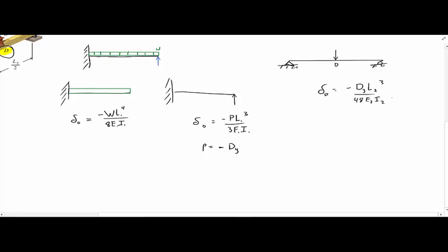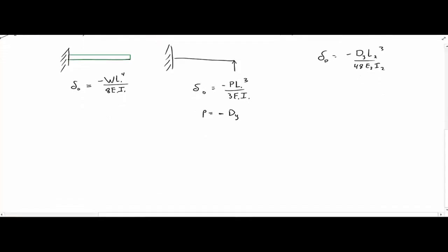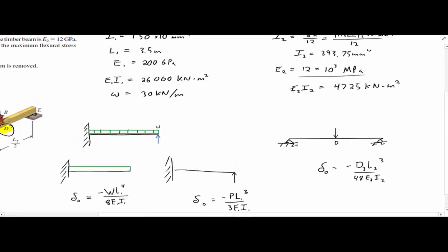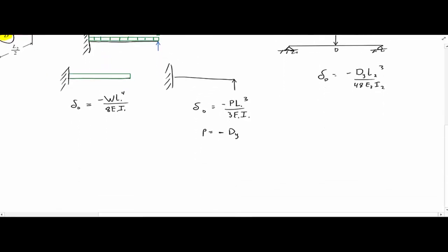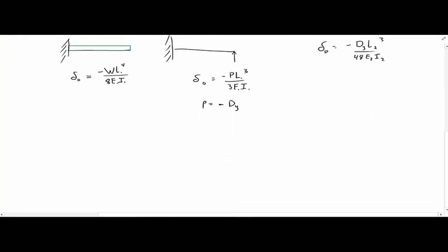So the deflections are going to be equal, or rather, we can equate them together to solve for the unknown, because everything in these equations is known. The distributed load is known, the lengths are known, the modulus of elasticity and moments of inertia are all known, and I even multiplied them together up here so they're already done. The only unknown is the reaction between the two members, D sub y. So let's relate these equations together.